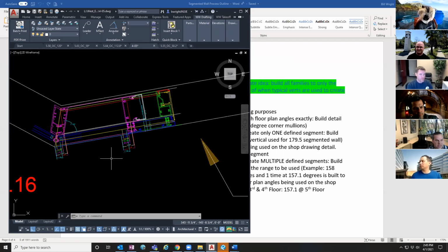And if the shop had cut them to just the first place after the decimal, versus doing it all the way out to 5 places past, in the end, that changed us hitting that other side. There was a 3-inch difference just by each end of a horizontal being mitered a sliver of a degree wrong. Yep. But depending on the size of the segmented area, it really adds up. And because it's angular, it really can cause some problems. So, yeah.